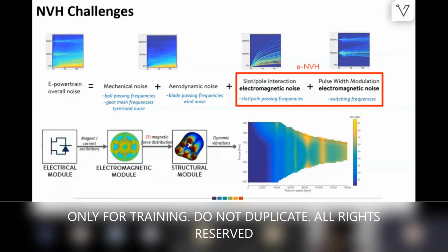We can do some interesting studies, like across the torque-speed curve, where there is more pulsation. And obviously, as I expect, you will have challenges at higher speed, with those harmonics, and that is quite obvious. So you can see at what level; that is the quantitative analysis we have to do.